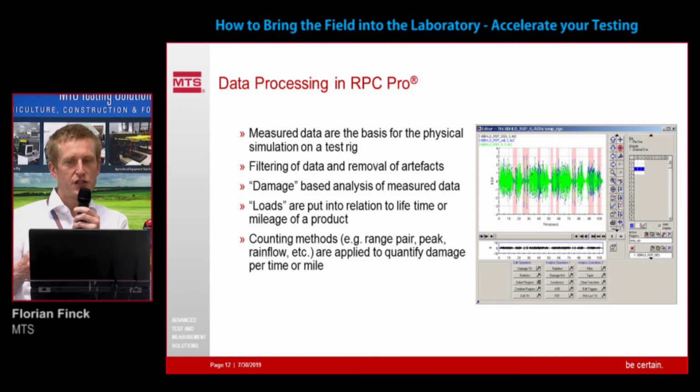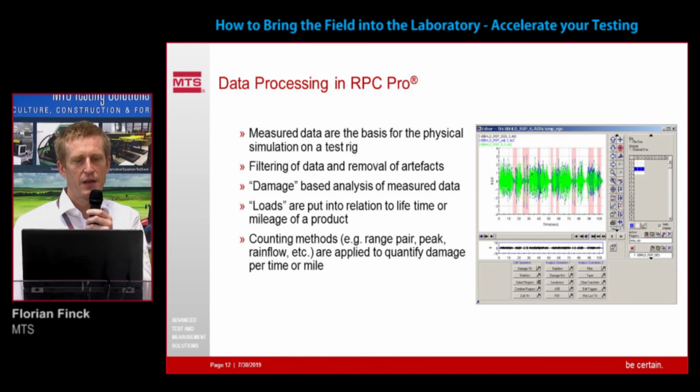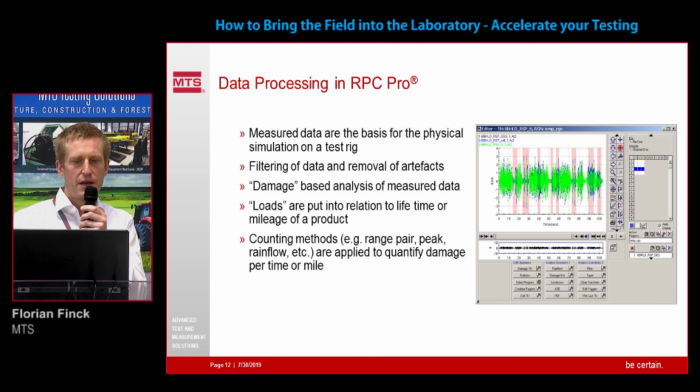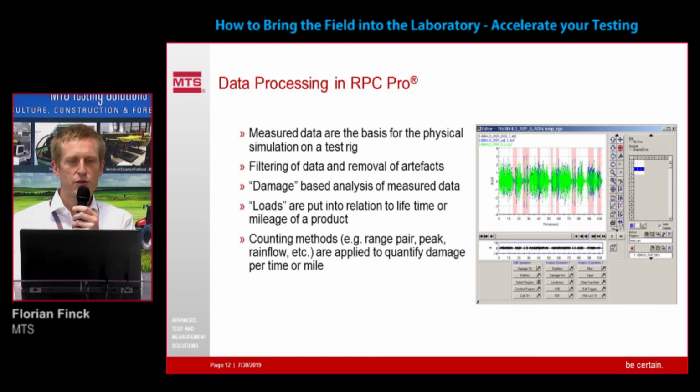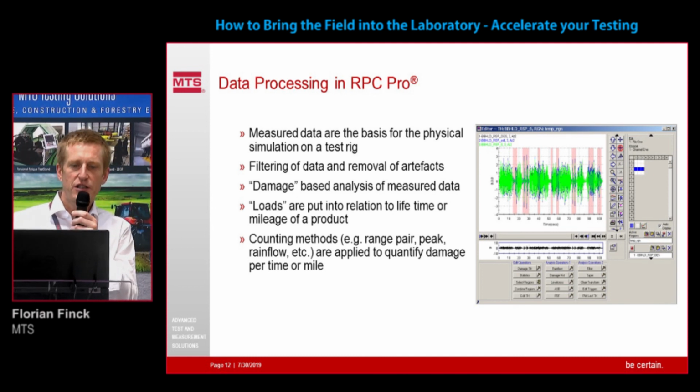You maybe want to cut out areas that are not relevant for the specific test. And then you will do something like a damage-based analysis of these measured data, so some fatigue analysis. Loads will be put into relation with lifetime or the mileage, and you will apply counting methods like range pair or rainflow counting methods that quantify damage per time or mile.